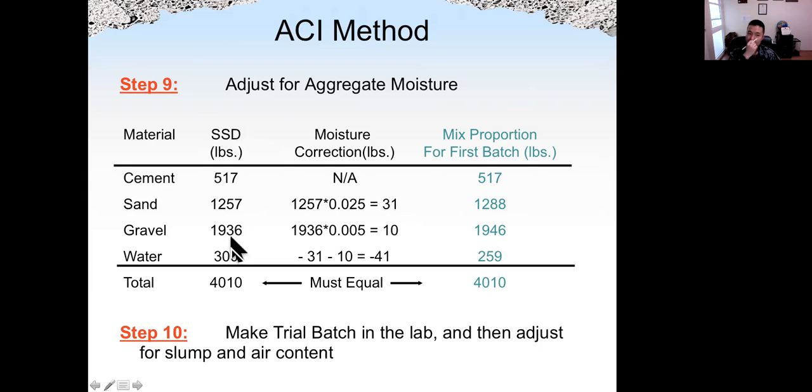Because the sand and gravel are wet, they can provide some actual water to the cement. That increases the water cement ratio if you do not adjust the moisture content. How much more moisture can the sand and gravel provide?